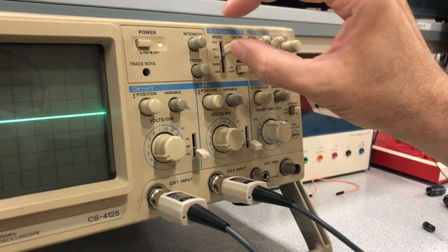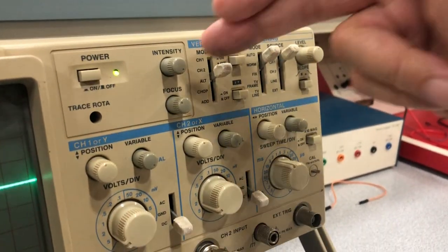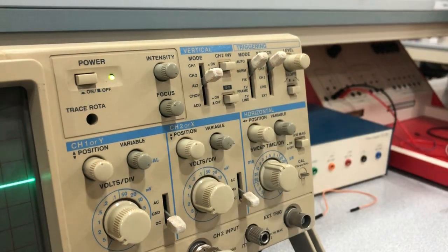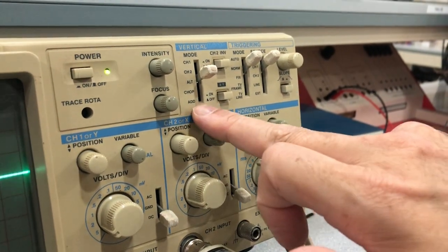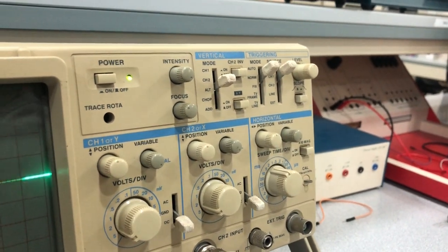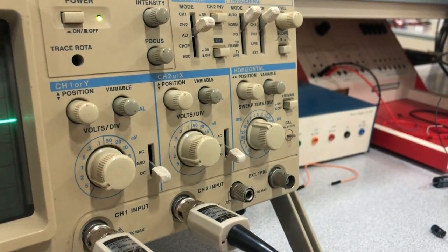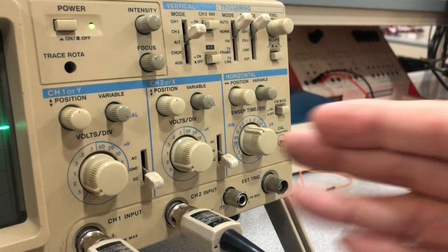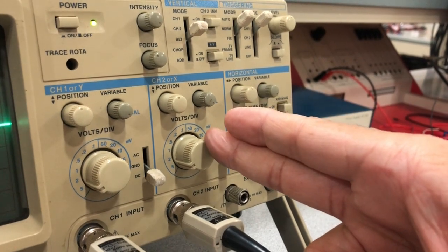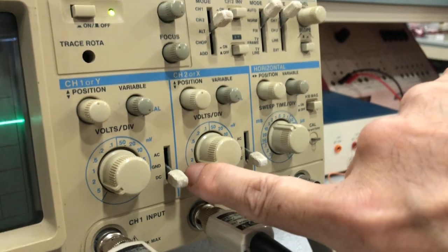So now we've covered the vertical mode to be able to plot channel 1 by itself, channel 2 by itself, or alternate between both channels, or chop between both channels, or do an addition on both signals or subtraction. Here it's symmetrical, I put both of them now on DC and both on 5 volt per division. You can have a different voltage per division on one channel, but you have to know what you're doing, and